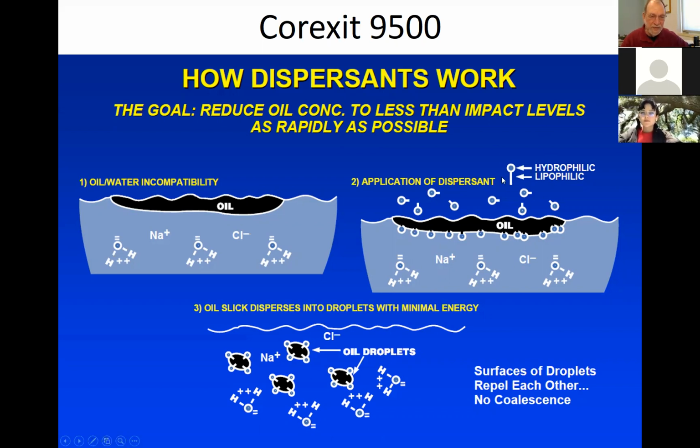Well, the same thing can be operated with this powerful detergent. And so Corexit 85 is basically a mixture of Tide, and they mix it with a carrier. So you could make your own dispersant with laundry soap and kerosene. You would get a dispersant. And they sprayed huge quantities, thousands of gallons per day of this dispersant. What the dispersant would do is form these little lumps with dispersant on the outside and oil droplets on the inside, and that would stop the oil from sticking together and allow it to disperse in the water column.